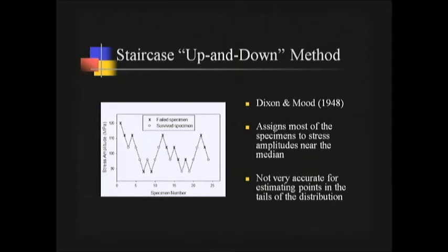Professor Lohbauer showed us this morning that if we do not fail by 10,000 cycles, or a certain number of preset cycles, then we will increase the stress that we subject the next specimen to. And if we do fail before that time, then we will decrease the stress. So the X here means that we have failed before the predetermined number of cycles. And instead of testing a whole group of 40 specimens at this level, we will go ahead and drop down to the next level to test the next specimen.